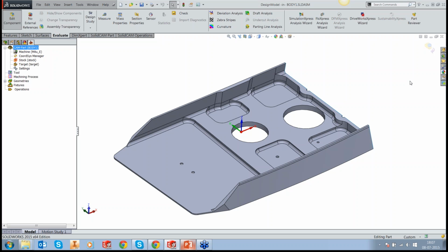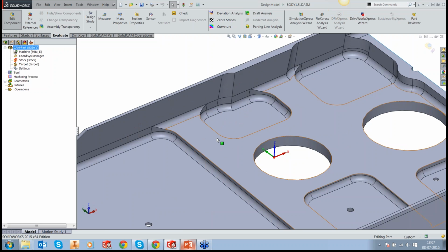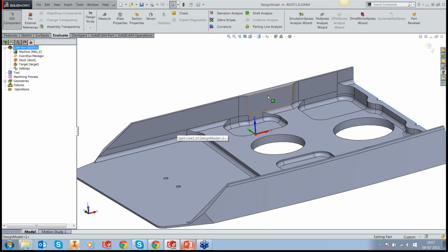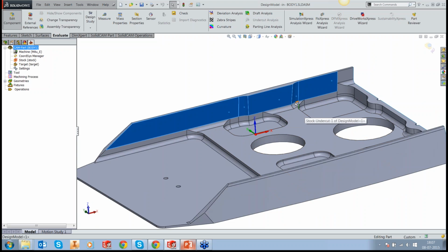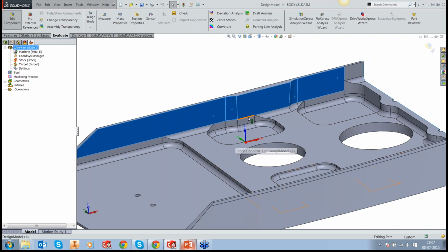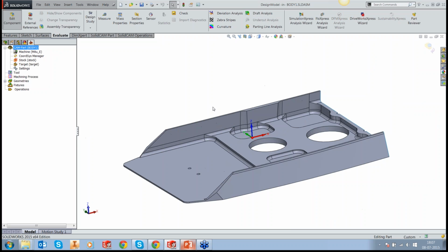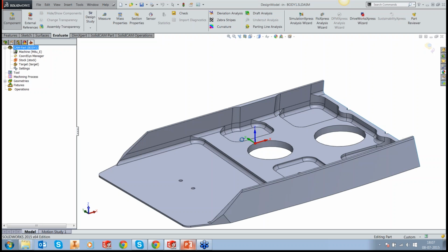Okay, what I've done here only is that you need to be a bit careful. This surface was actually one single surface. Okay, so what I did was I just sliced, or I split the surface along this fillet, so that I get a good homogeneous surface out here to work with, and then I can handle this surfaces separately after we finish the top surface.